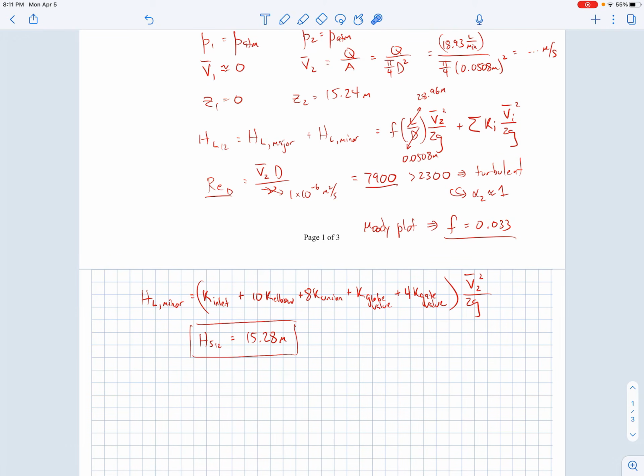They're just very small. The flow rate through the system, if I did all my numbers correctly, just doesn't result in very large major or minor losses. They're just small in comparison to the elevation head difference. Now, if we had a higher flow rate, then those major and minor losses would be more significant. And then this value would be bigger because we'd have not only the elevation head we have to overcome, but we would also have larger major and minor losses. So by noticing this, it just means that we're really just mostly overcoming the elevation differences.